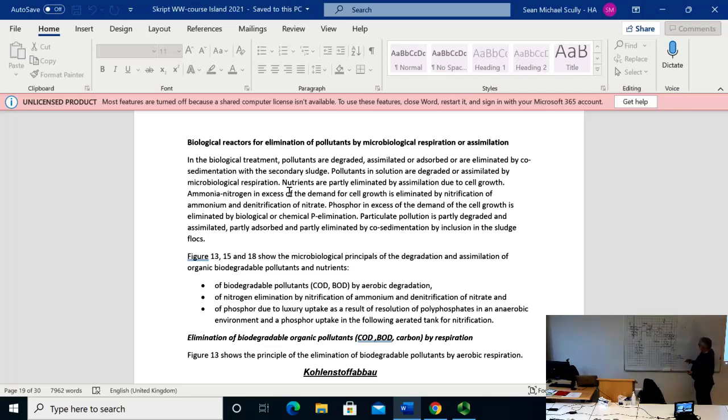Right. Then we have here 98 liters, no? Because 1 liter's gone here and 1 liter's gone here. Those 2 liters go into the digesters, and really those 2 liters almost come back completely as well, because after the digester we have another dewatering of the digested sludge. So 90% of those 2 liters come back as a filtrate from the dewatering of the surplus sludge. So really, this is almost 100 liters, no?